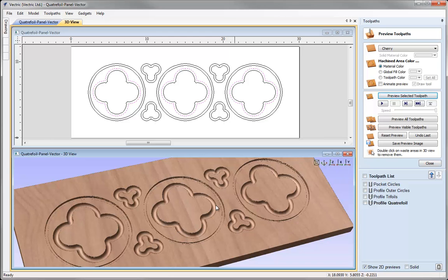The next toolpath we're going to be concentrating on is also going to be using a 1/2 inch ball nose. It's wise to keep all toolpaths that use the same tool together, so that when it comes to saving out the toolpaths at the end, we can save them all out as one file. So it makes sense for us next to finish off our ball nose toolpaths.